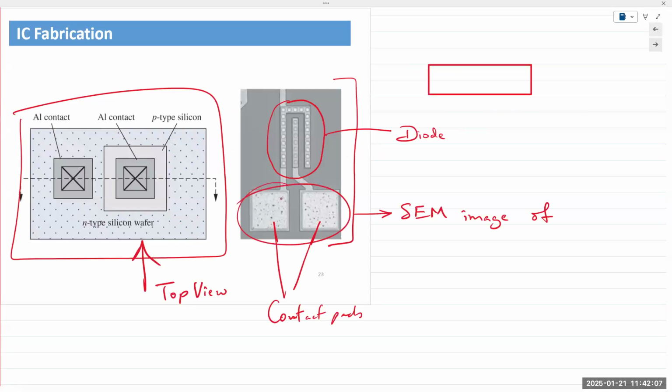Okay. So there is an insulating material. This is an insulating material. And more often than not, it is simply silicon dioxide. Silicon dioxide is very easy to grow. We simply take our silicon wafer, stick it in a furnace at 1000 degrees C, silicon with an oxygen environment, silicon bonds with the oxygen atoms, and we get silicon dioxide, glass, which is an excellent electrical as well as thermal insulator.